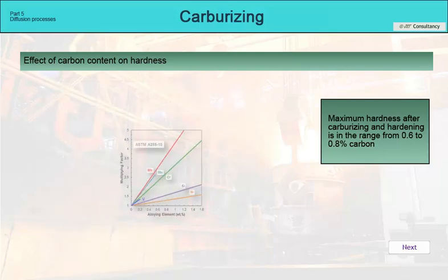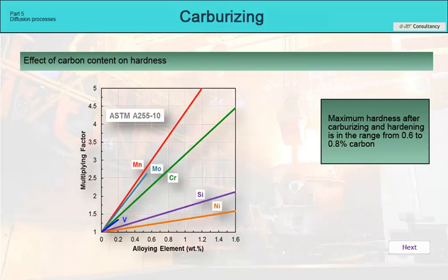The second factor affecting the hardness of the layer is the content of alloying elements in the steel and their type. In general, this hardness increases slightly with the content of chromium and molybdenum or manganese. This is due to the fact that with these alloying elements, the amount of hard carbides formed by them also increases. On the other hand, nickel or silicon change this hardness only minimally.